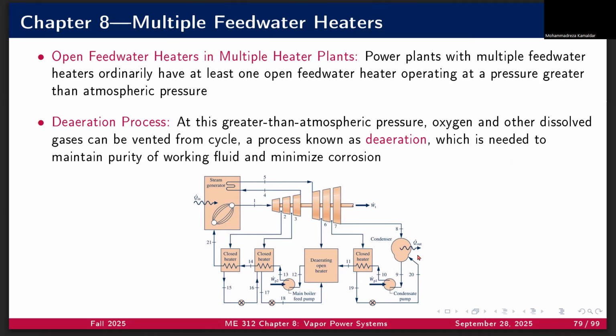This open heater is strategically placed to operate at a pressure greater than atmospheric pressure. The primary reason for this is to facilitate a crucial process called deaeration.